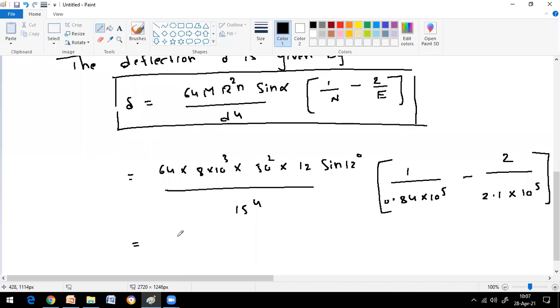What is the deflection number? So you will get a value of 15 mm. Okay, you can calculate 15 mm. Now we will try to compare the deflections which you got based on the axial load and the deflection based on the torque, I mean axial torque of 8 Newton into meter. So for which load is your deflection more? For the torque or for the axial load?